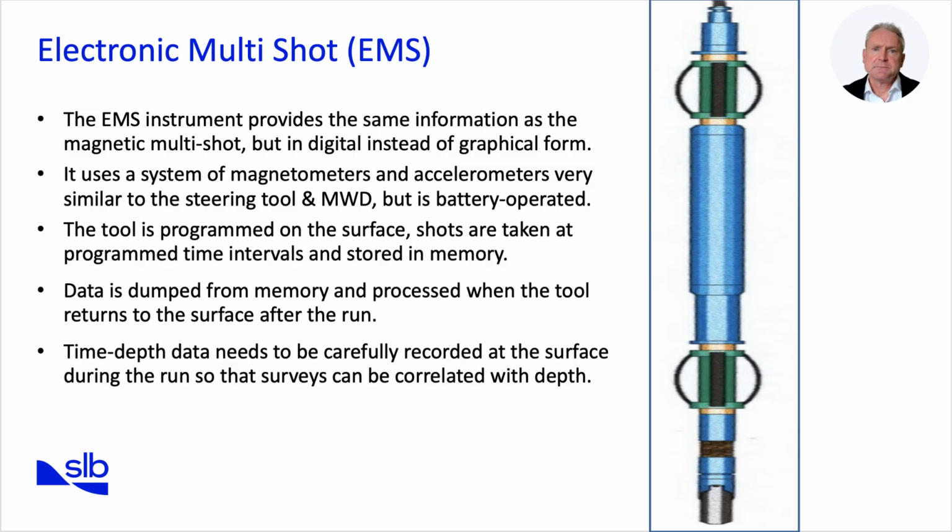Therefore, EMS is best used in environments where cost control is key and real-time steering is not required. It remains popular for lower budget or simple wells, or as a backup when MWD is unavailable. EMS demonstrates how digital technology streamlines survey processes, eliminating film while preserving affordability. It represents a middle ground between old-style single shots and fully real-time MWD systems.